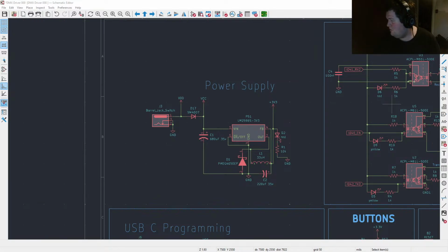They use RFB 505S, which is, I'm assuming, a 5 volt to 5 volt Recom isolation module. Outputs 5 volt 200 milliamps. Its input voltage is 5 volts. Okay, so it's similar to what I want.